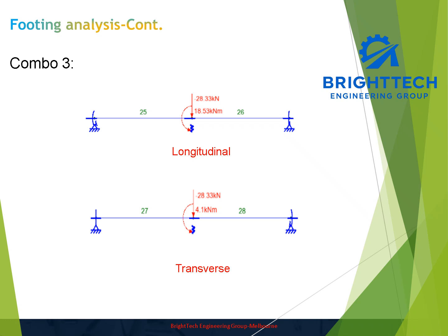We just applied the forces that we already calculated and used in the structural toolkit. We also applied them on the footing here in Space Gass to check the strength of the footing. We used the structural toolkit to check the stability and dimension of the footing. Now we need to check if the footing has adequate strength to withstand these loads or not.